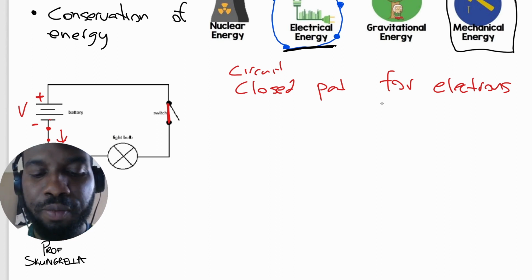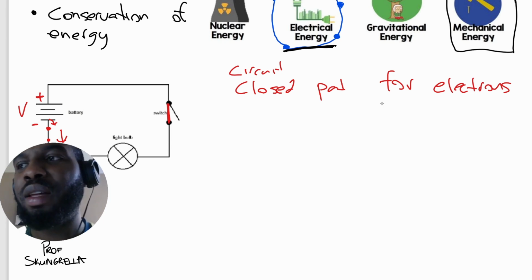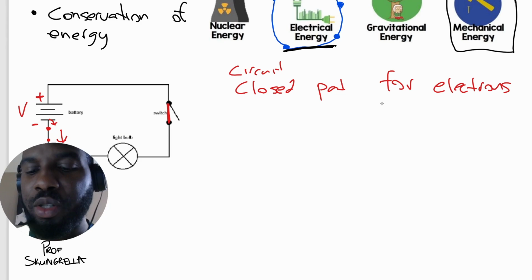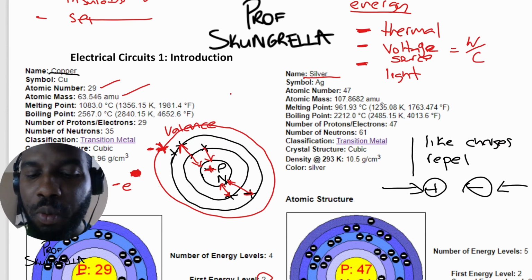So they're going to travel, and as the free electron travels, it collides with other electrons and it loses that energy. And so what it's going to do now is recombine with another atom, and that can be an atom that is neutral. So again, we said that we can have free electrons, right? When that electron leaves, then we have a net positive charge in this atom right here. And so this atom now is attractive to a free electron, that a free electron can also recombine here, right? So we have this separation happening, the generation of free electrons, and we also have the recombining happening.